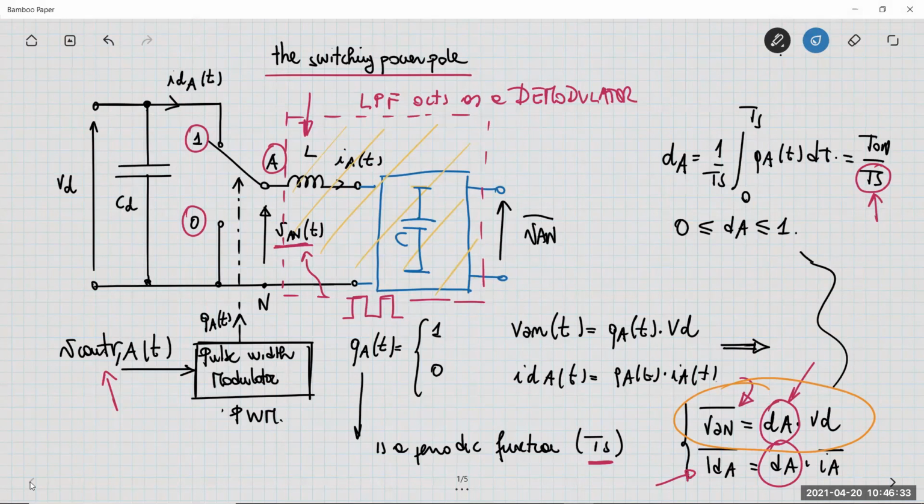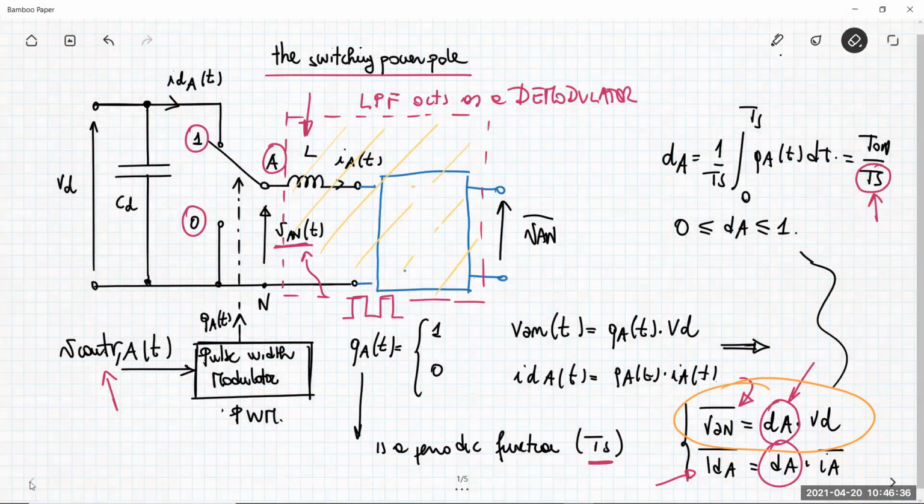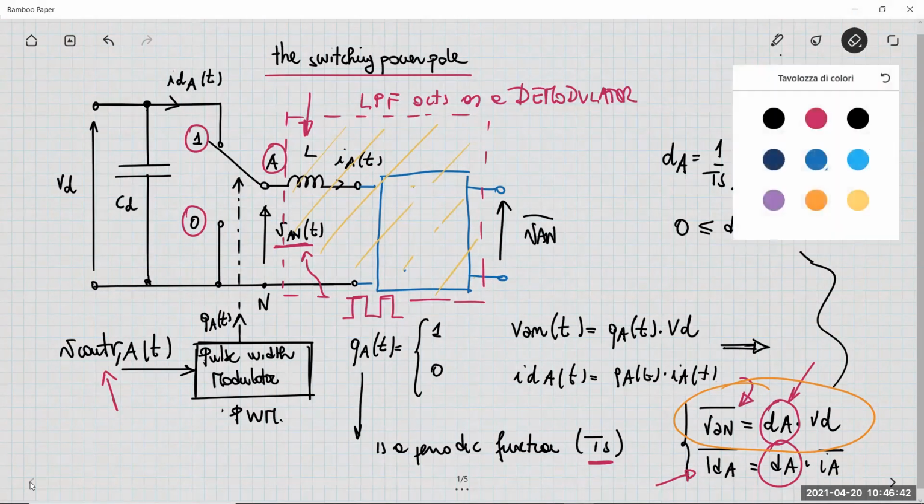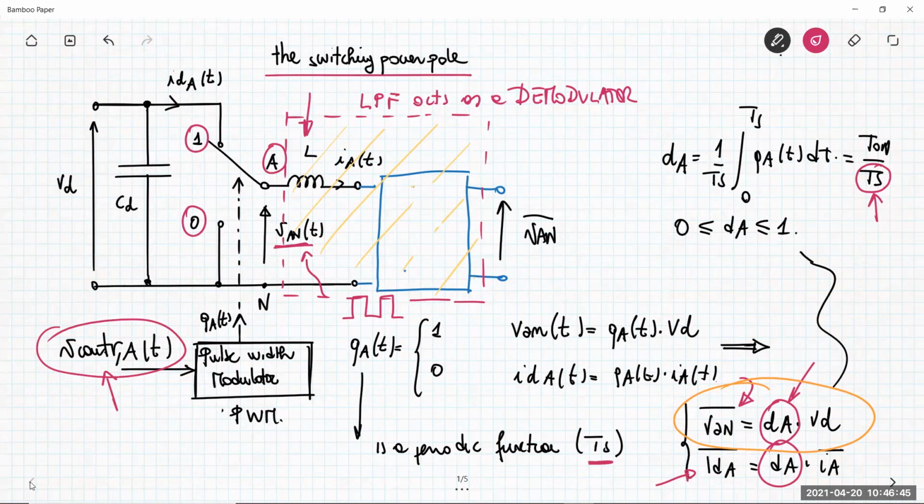So basically the process is using this control voltage at the input of the modulator to transfer the information of the control voltage into a modulation of a duty cycle, generating a highly distorted signal by using this sort of amplifier, and then considering a demodulation action on this waveform to extract the information I need the most, which is the average value of the voltage, because this is a quantity that can be directly modulated by the control voltage.